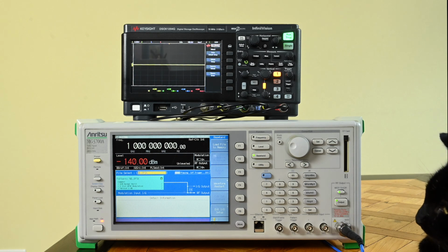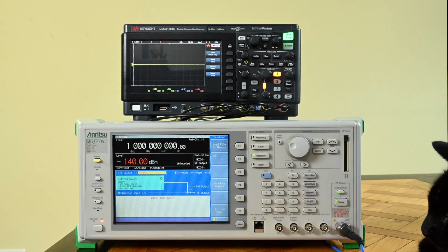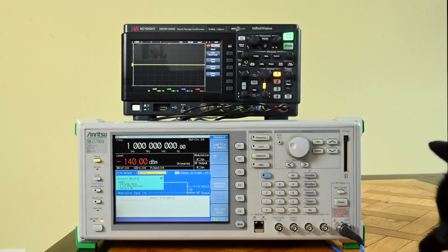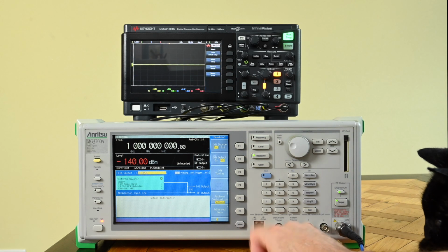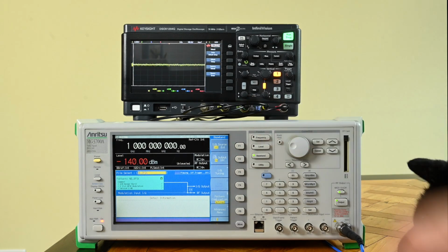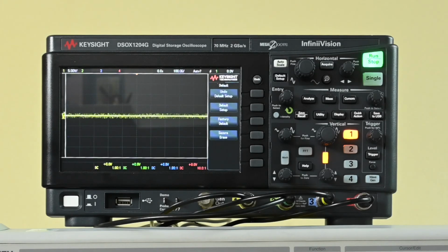Now, for our experiment, I'm not going to look at the RF output yet. I'm going to do that in a second, but I would like to look at the IQ signals which come out of the back of the device and for which I made some adapter cables. If I want to see these IQ signals, I'm going to do that on the Keysight scope here, which actually looks like a dwarf compared to all these large 19-inch machines here. I have to go into this menu and enable the IQ output. Then push it well. And there we go, we already see something happening on the scope.